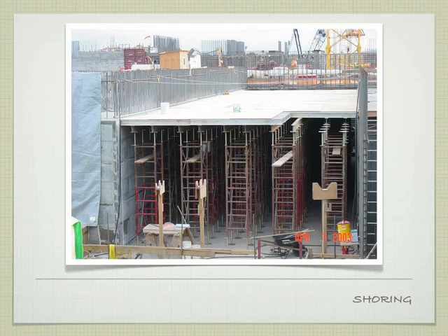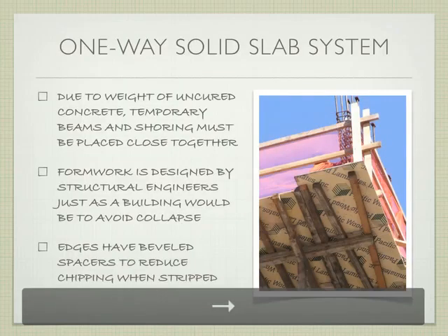These are all the little joists, and they're stacked up going back this way, that are then supporting the plywood. Below that, we have our beams that are running the opposite direction. Below that, we have our shores that are supporting that. Recognize we have to support a fair amount of weight when we're pouring that concrete.